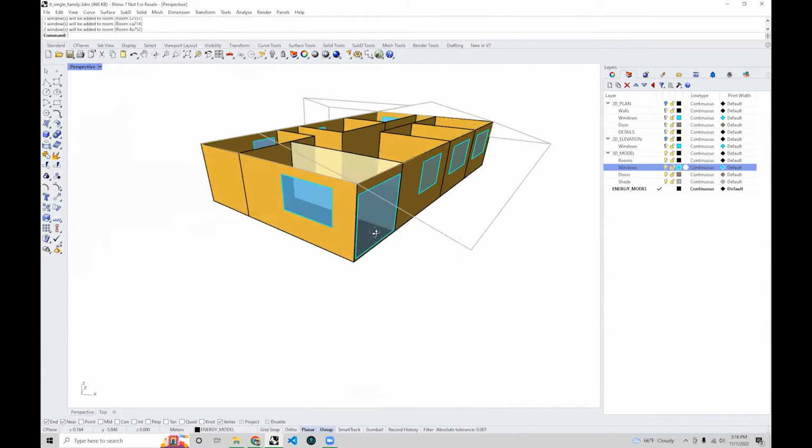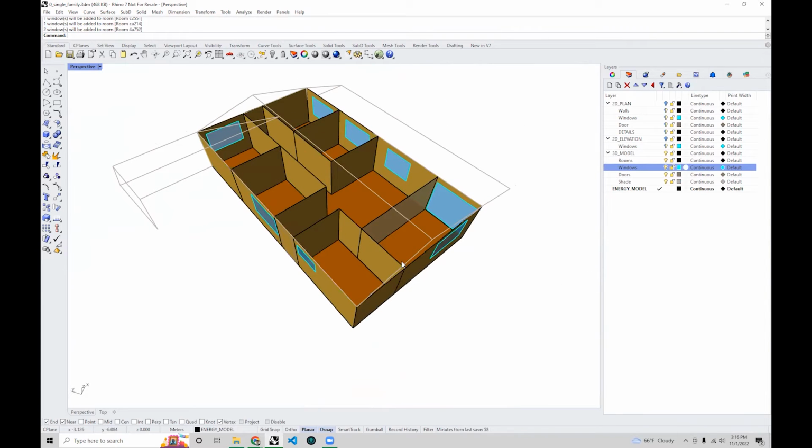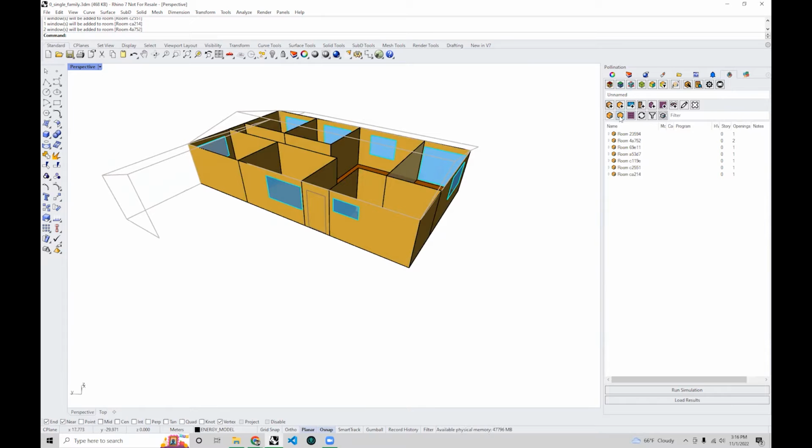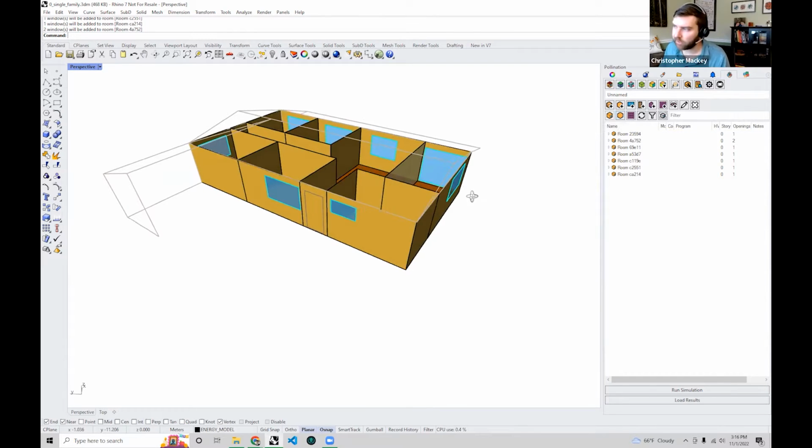So it looked like it was kind of partially added, right? Like some Z fighting or something? I think it converted them to apertures, but I guess it added them as orphaned apertures because I didn't actually select the individual room geometries. I had recreated it at my end, but it was weird. It was like you said, it created the aperture, but did not add it to the room. And I guess one way to double check is, what do you recommend? Maybe you could isolate the room, and if it doesn't pull the aperture with it, then you'll notice. That is certainly one way to check.